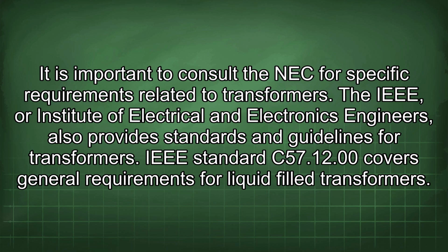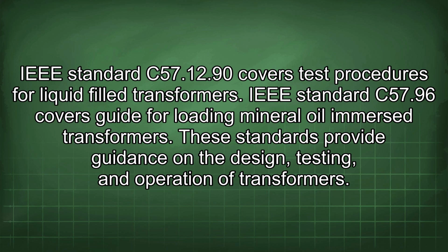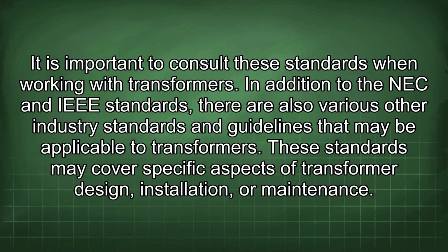The IEEE, or Institute of Electrical and Electronics Engineers, also provides standards and guidelines for transformers. IEEE Standard C57.12.0 covers general requirements for liquid-filled transformers. IEEE Standard C57.12.90 covers test procedures for liquid-filled transformers. IEEE Standard C57.96 covers guide for loading mineral oil immersed transformers. These standards provide guidance on the design, testing, and operation of transformers. It is important to consult these standards when working with transformers.